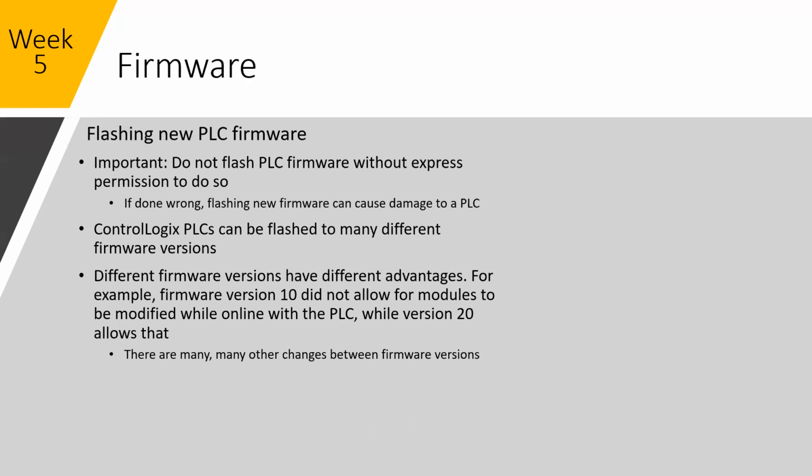There's even specific firmwares. So if you start doing redundant controllers, you have to look at putting on specific redundancy firmwares. So if you're ever going down the redundancy rabbit hole, you do have to pay attention to what controllers you have and pick the proper firmwares for the other cards that you're going to be using.